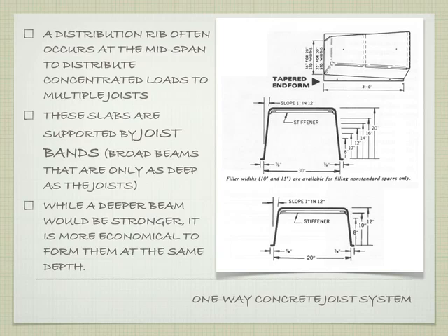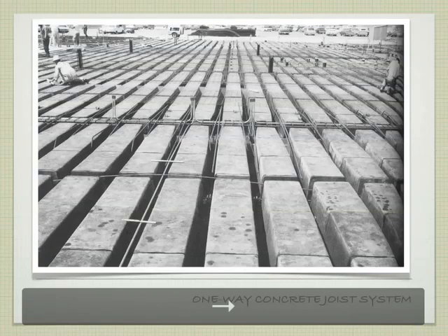So if you think about the formwork for building something like this, it's really simple because you have the column come up, and then on top of the column, you just build a big flat sheet. And then you build this whole slab system on that flat sheet. So there's not all the formwork of doing each of those individual girders. So it ends up being more economical to build something like this from a formwork standpoint, which is one of the big advantages of doing this.